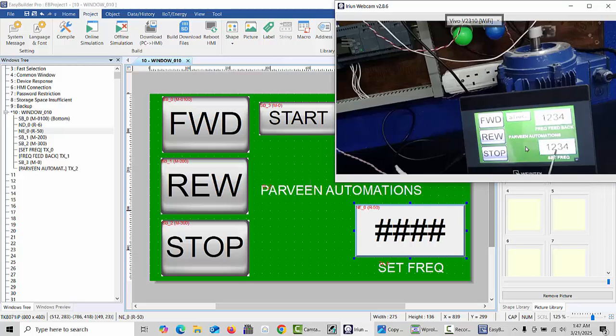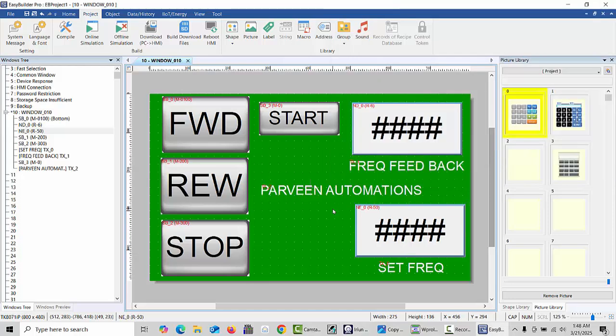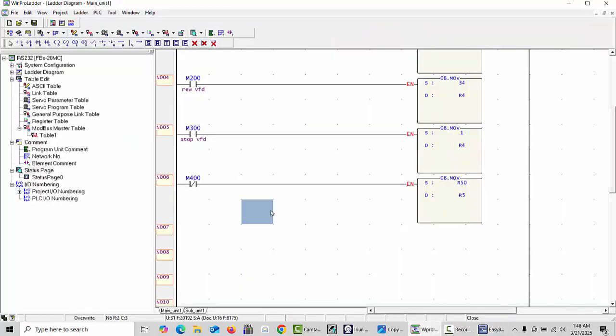And if you like to change this value, for example 1500, we would like it to change so that the VFD goes to 10.5 hertz instead of 10 hertz. How we can change this data, I will also explain to you. For this we have to use the math function in the PLC. I have to change this data here.